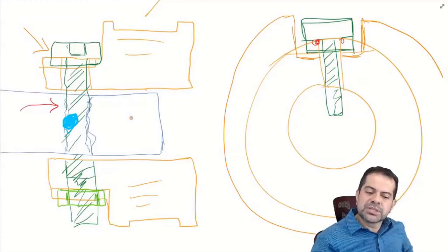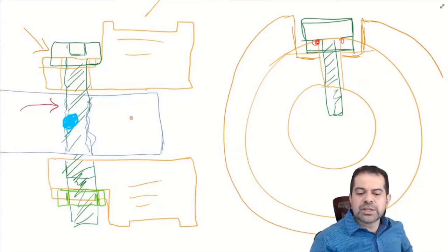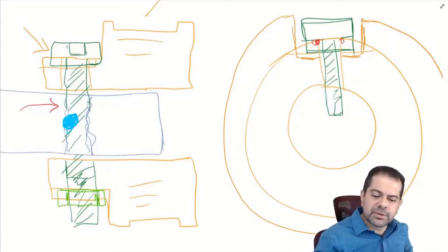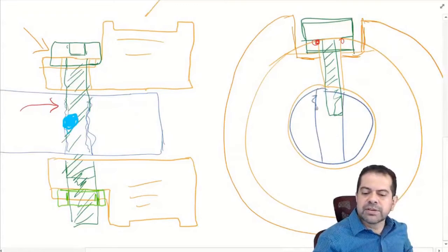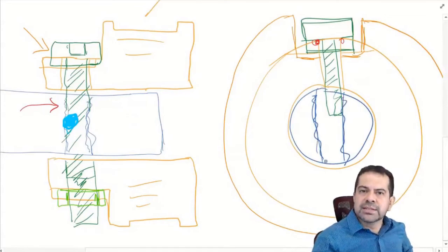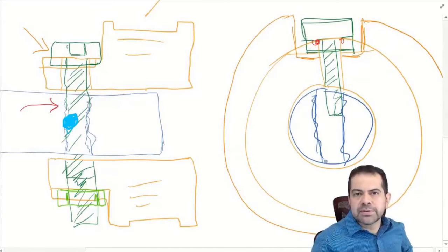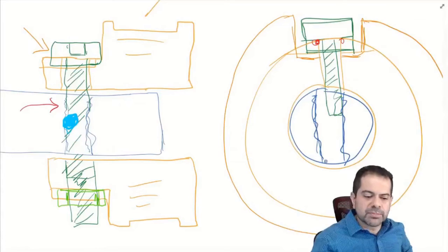Another thing, once again, coming back to forces, if you're dealing with high forces, in drilling a hole through a shaft, let me draw it over here. Drilling a hole through a shaft and then tapping it, you have weakened that portion of the shaft. It's a little bit weaker. So you have to determine if that's okay or not, if that's acceptable or not.